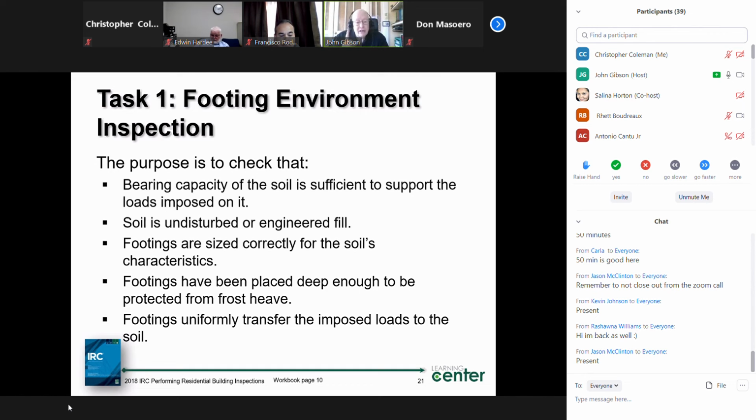The big trick is once I go to the IBC, generally, I'm going to expect that you got the sprinkler system in the building, whereas the IRC does give me provisions if you choose not to put the sprinkler system in the building. So some big consequences there.